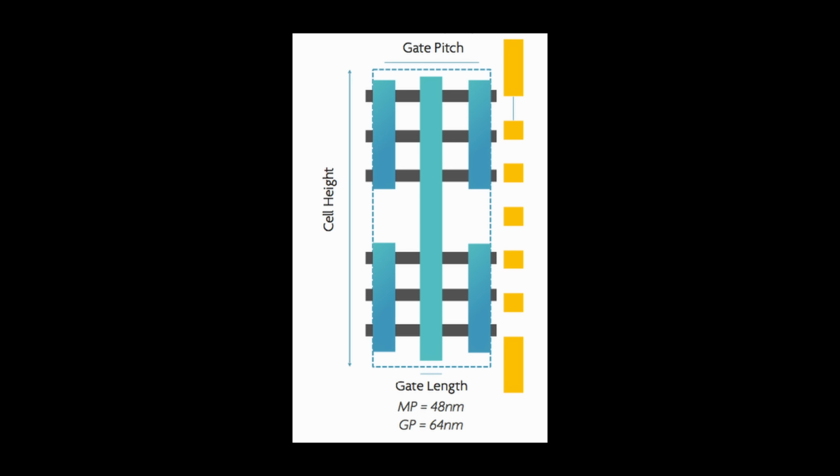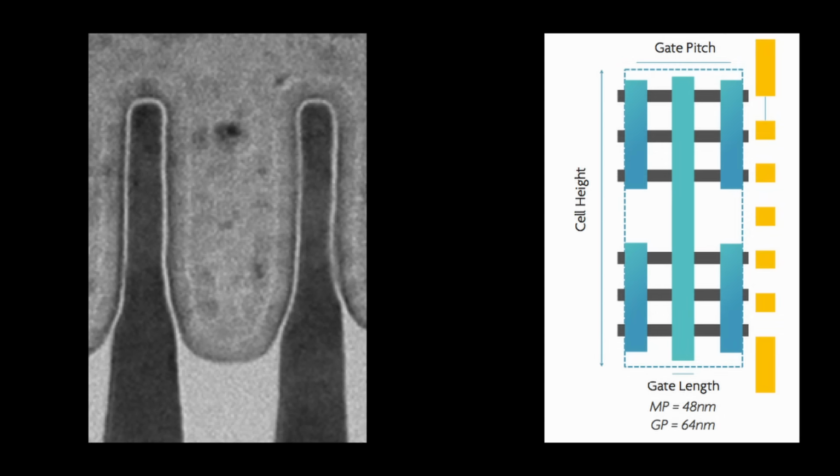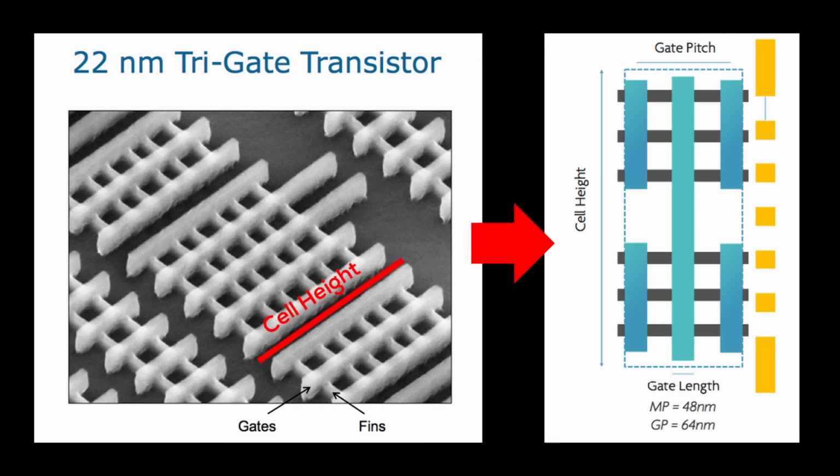When it comes to the size of cells, the next step up from transistors, the most important variable is the cell height. Though the term cell height is a bit confusing, because unlike transistor height for FinFETs, we are not actually talking about height as in going upwards from the silicon wafer. Instead, the layout of most cells is depicted by looking at the cell from above. In this view, cell height is more akin to cell length. Reducing the fin pitch reduces the length of the cell and thus its area.